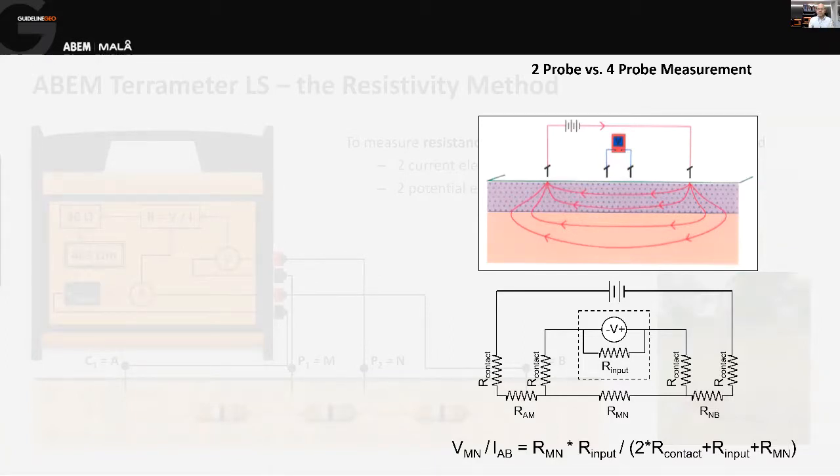If we have a small current flowing, the measured voltage that we get back is going to be very small. And if the measured voltage that we get back to calculate our resistance and convert to apparent resistivity is small, then it's at risk of getting lost within the electrical noise that is all around us, from electromagnetic transmissions like TV, radio, mobile phones, transmissions of the national electrical grid. All sorts of things generate electrical noise in the soils and the rocks beneath us.